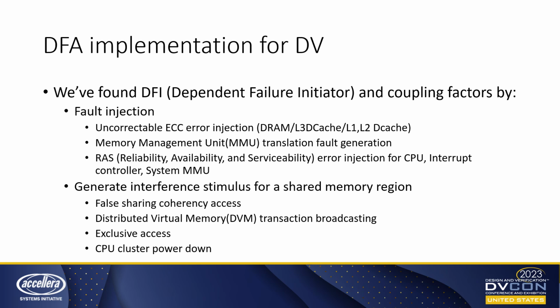Using these fault injections, we inject ECC errors and MMU translation faults, and we use the feature implemented from the ARM v8 architecture, which can generate internal error cases to the CPU, interrupt controller and system MMU.